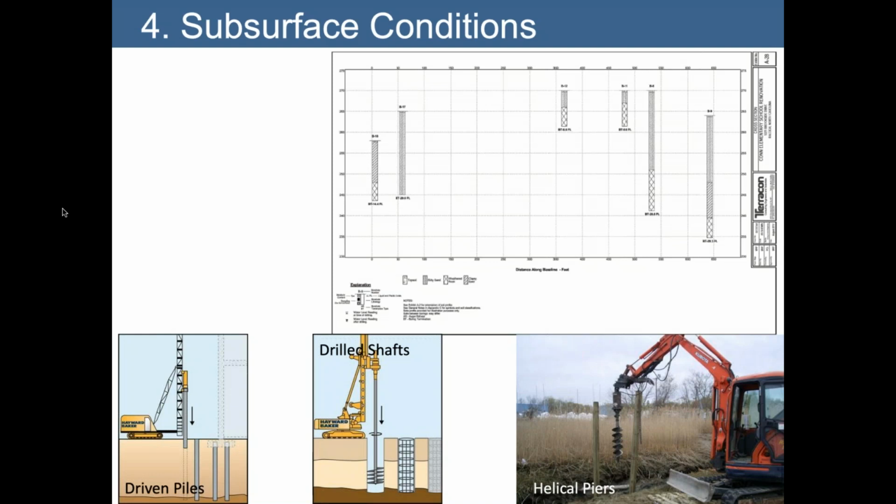I would advise that you take this on early in the design process, figure out with a geotechnical engineer's help, do that subsurface exploration. Go out there and hire somebody to do some soil borings where they actually drill down into the soil. They take soil samples, and then that geotechnical engineer can pull together design requirements. You know, is a driven pile a requirement, or is a helical pier the best suited situation, or possibly even a shallow foundation system?